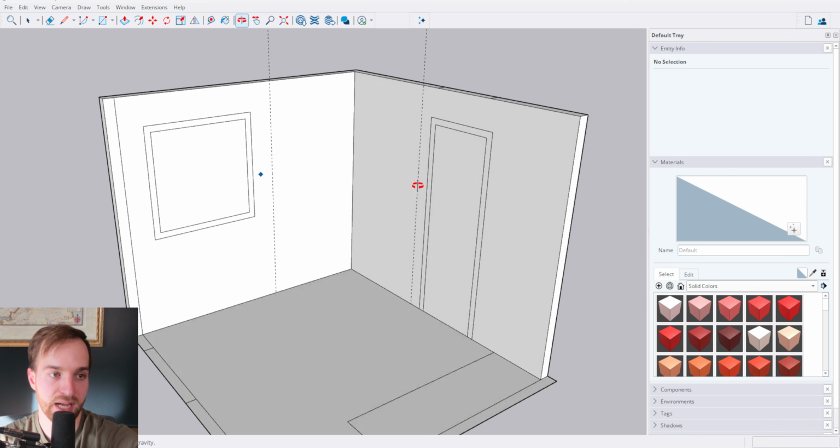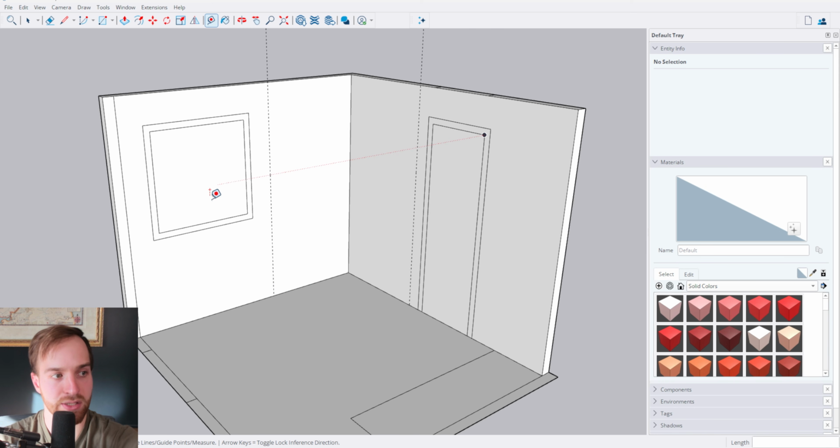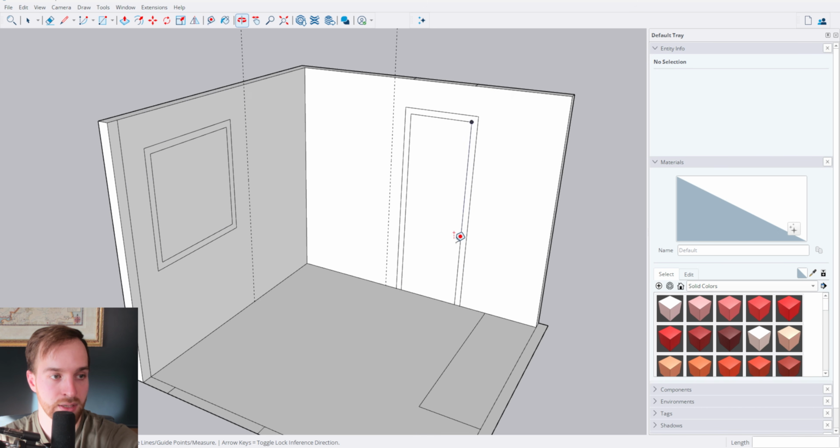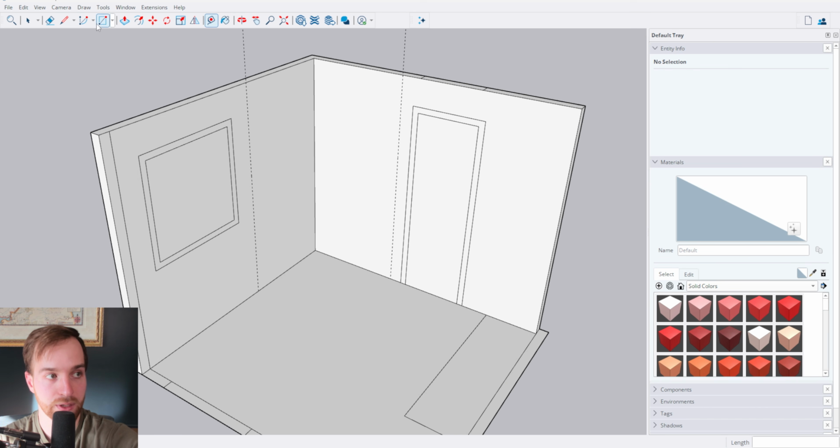And we got a bigger gap on this side than here, but I think that's okay. It kind of creates a nice effect with this window in this space, and it keeps the shower symmetrical, 44 and 44, and I do like that. So next I can take my line tool and just kind of mark out those measurements now. And I can even draw it on the floor.